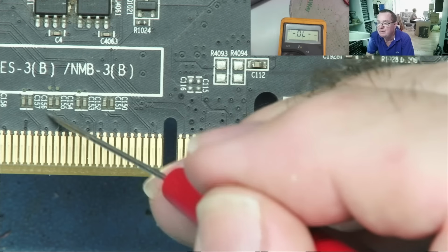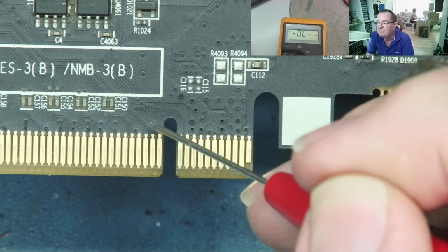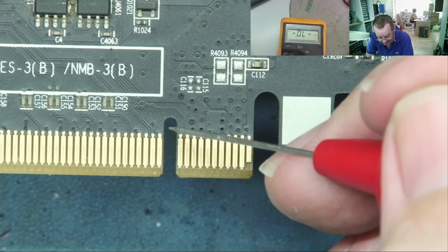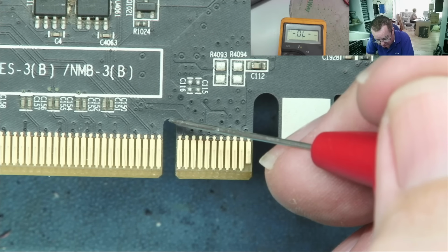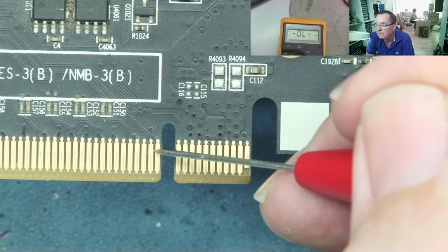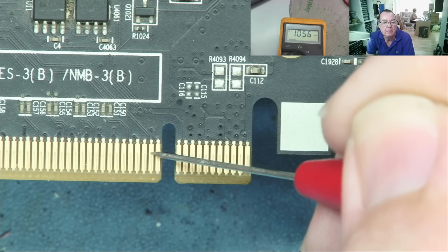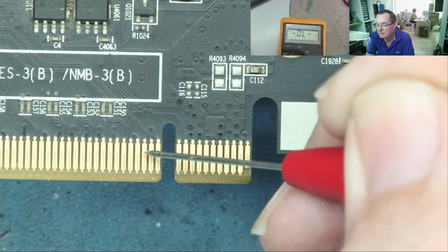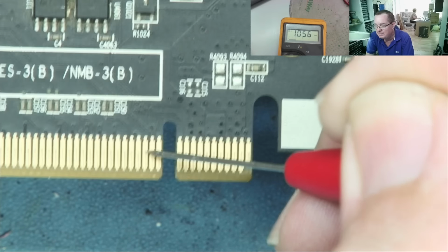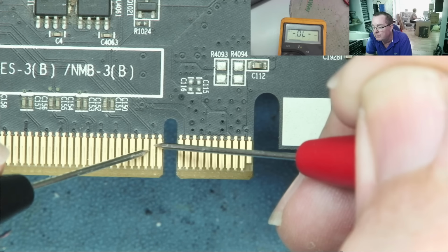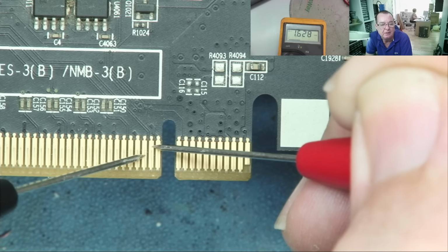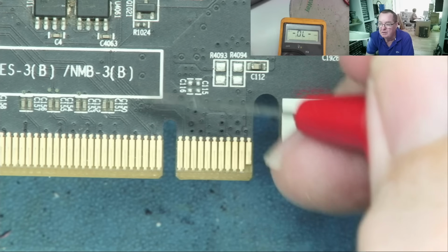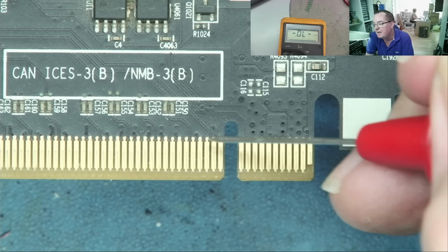Again, you'll see the 16 lanes with pairs of capacitors, and then you'll see this lane which doesn't have any capacitors. This is the clock. Again, this is the one that's most susceptible to damage, together with lane 1 on the other side. So that reads different, 1.057. The other one read 810. But they both read the same as each other, and they're not shorted to each other. So I'd say that's okay. I mean, without having another card of the same, to be certain, but that's a very good indication they're okay.